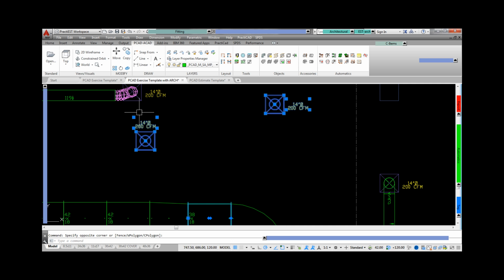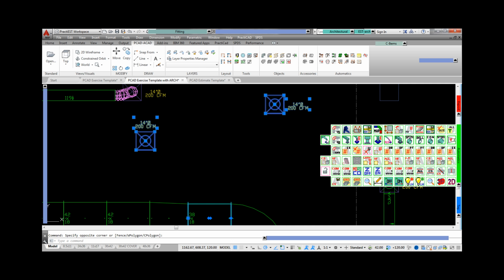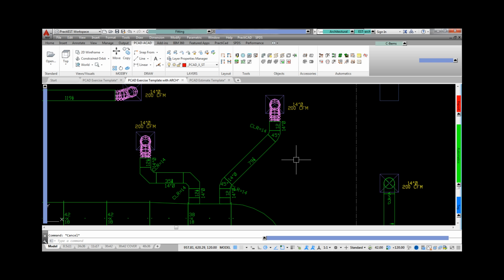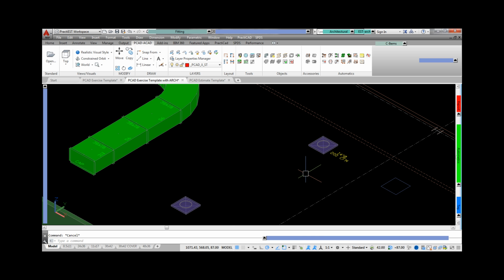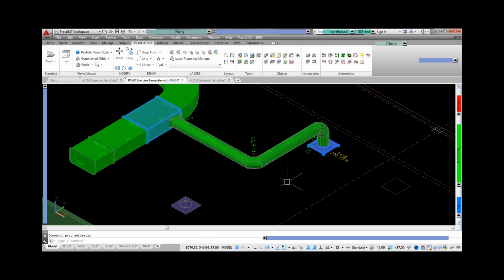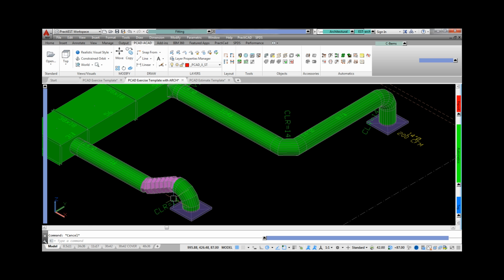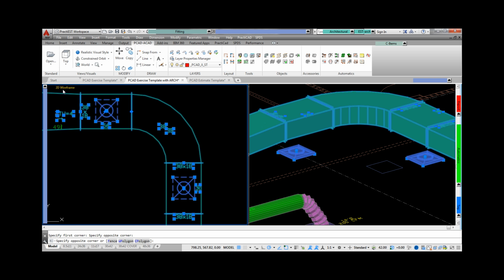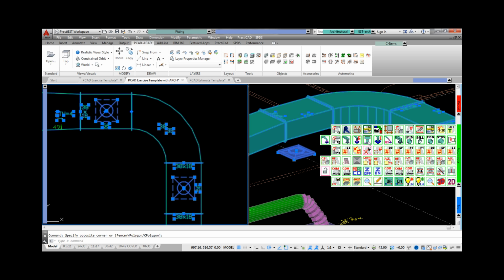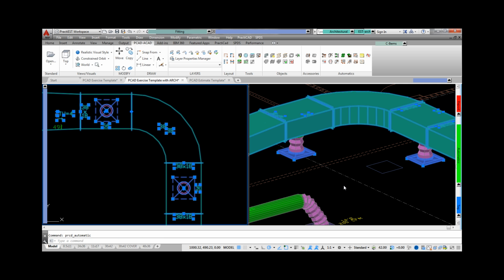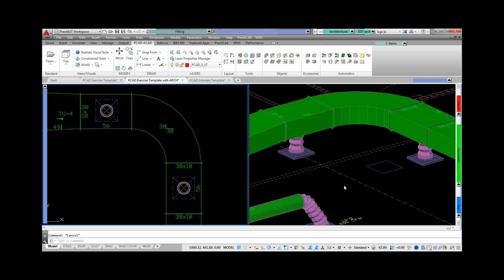The first route's one turn at 90 degrees, the second route uses two turns with 45-degree elbows. If the engineer requires a hard pipe connection or doesn't allow for you to bend flex on the GRD, then simply adjust your route accordingly. Hard pipe options and options that require an elbow, no matter how far the drop, are available. Dropping it down to some GRDs lying under the duct has never been easier. Just window select and route.